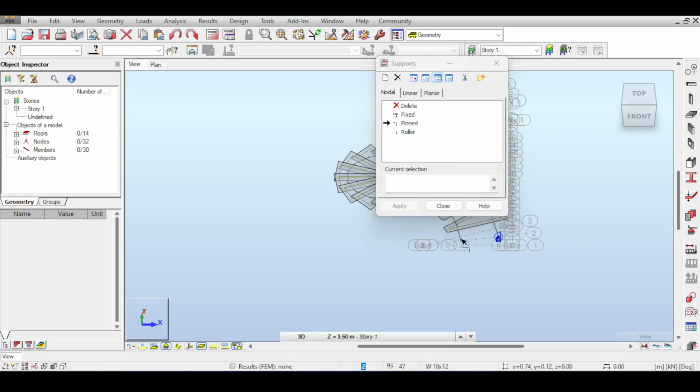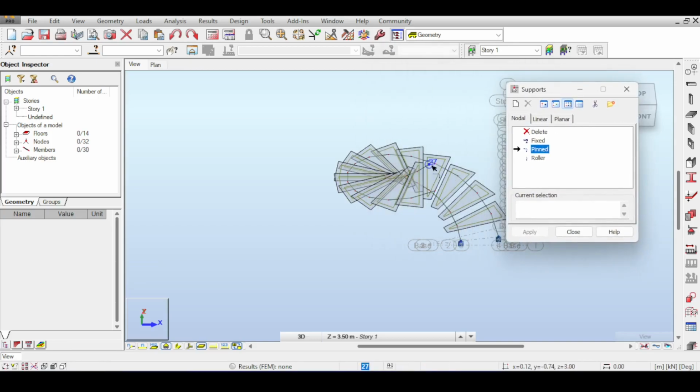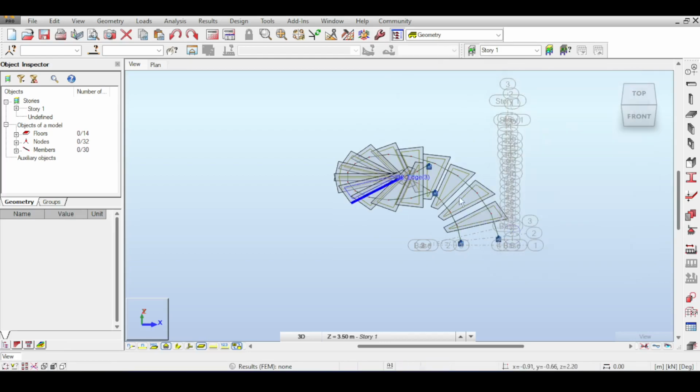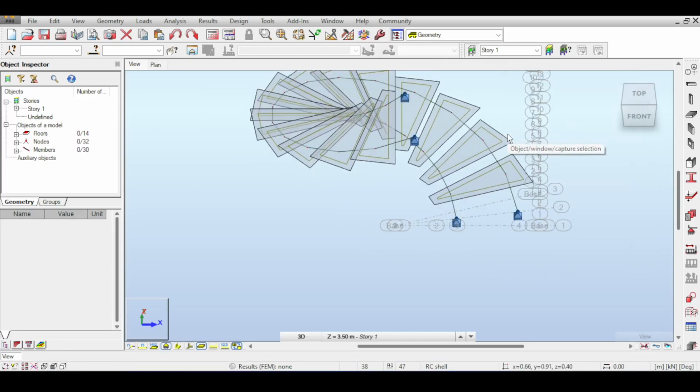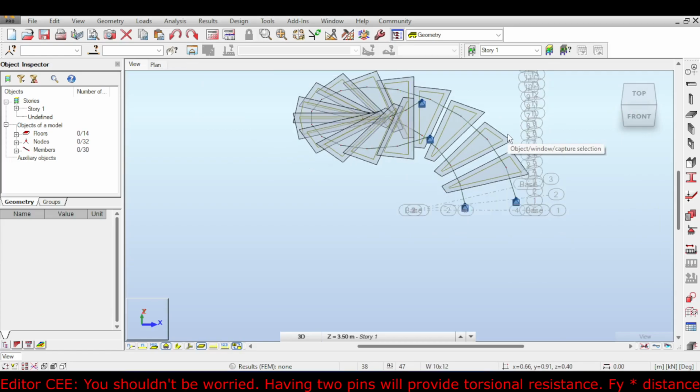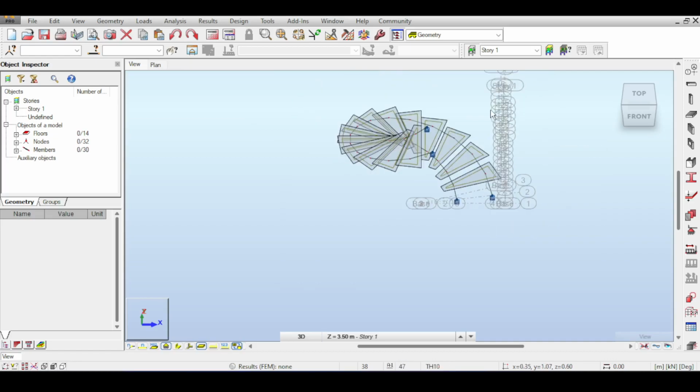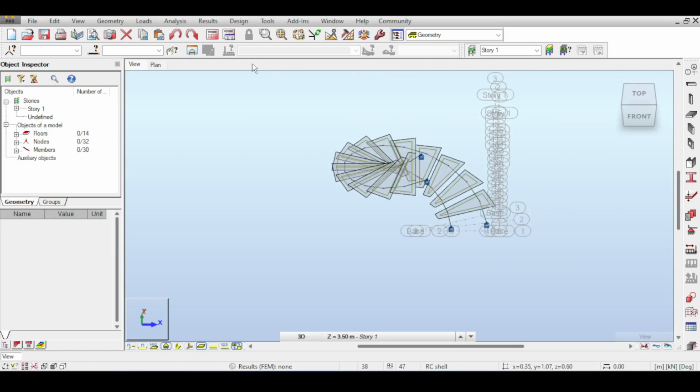So here is a pin, here is a pin. Will it be stable? Will pin stabilize it? Let's take a look. Well, torsionally speaking, I don't know. I have some worries. I think this is unstable. I think I should put fixed here because there are some rotations involved. Let's take a look. Of course, we need loads, so I will run the analysis dry run here because next time I'll apply the loads and whatnot. For now, I'm just modeling.